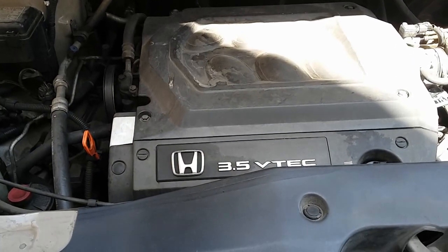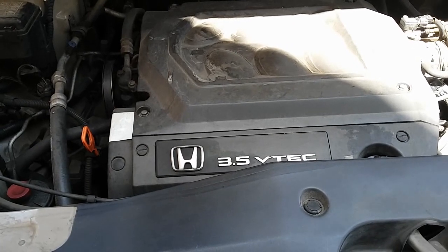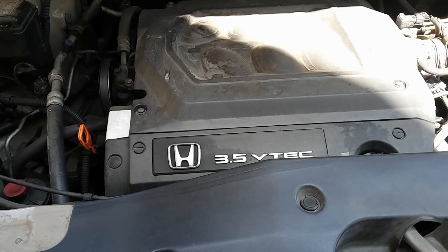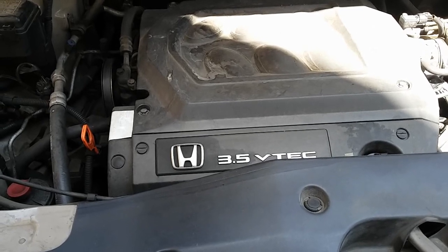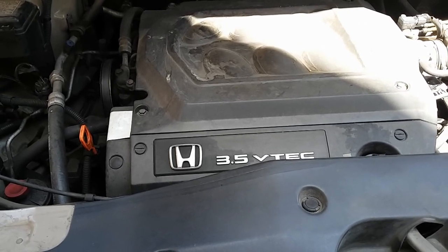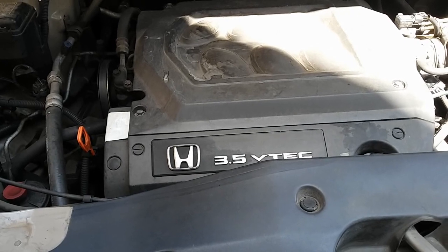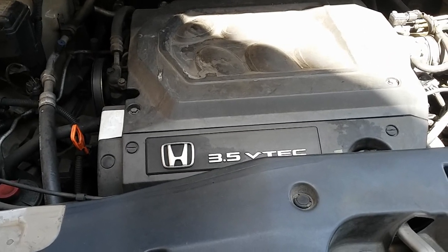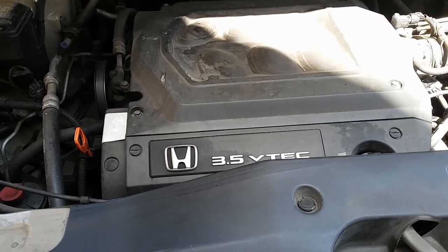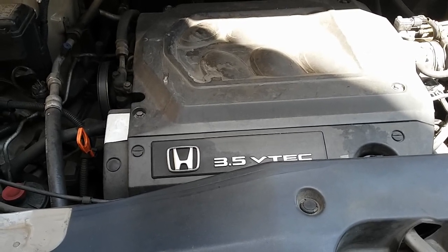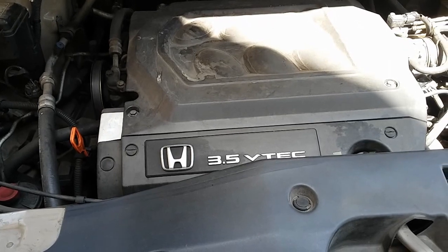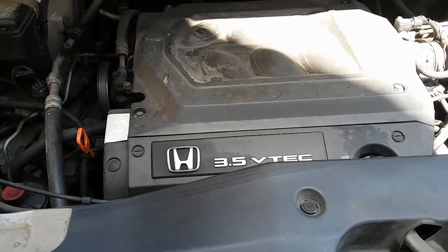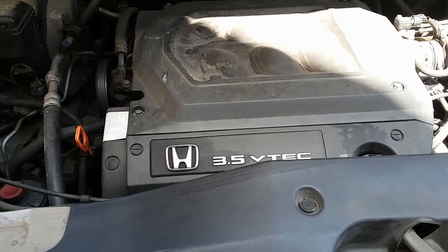Alright guys, so after performing these 3 methods that I showed you by using a scan tool, an infrared laser gun, and an exhaust back pressure tester, pretty much all 3 methods show that the catalytic converter is still working properly, still working efficiently. I'm thinking this is an intermittent issue, where the computer triggers this P0420 when at times the catalytic converter is not working to its potential efficiency.